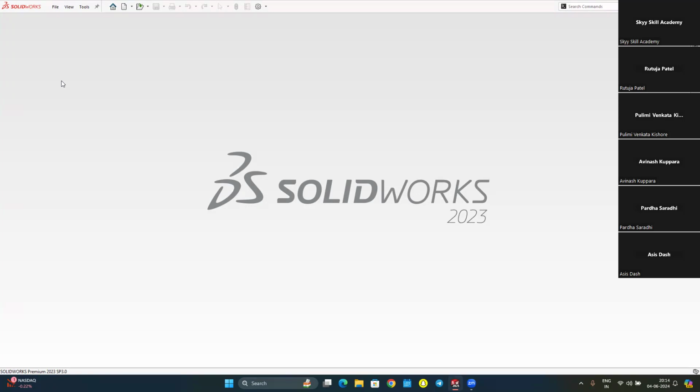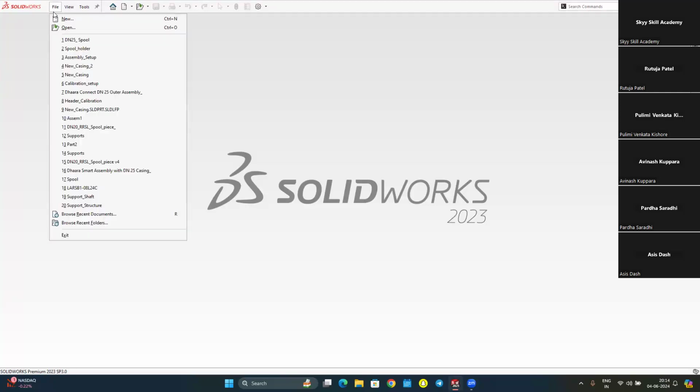Okay, and as someone said, K factor. The K factor is the ratio between the thickness of the metal and the bending radius. That K factor will be 0.3 to 0.5. So mostly it varies from 0.3 to 0.5. Sometimes the software calculates it automatically, in some softwares like CATIA, the K factor is calculated automatically when you give your thickness and define your bending radius.